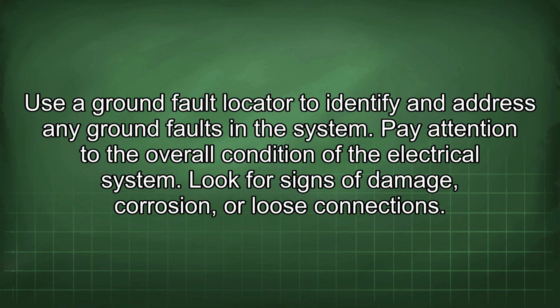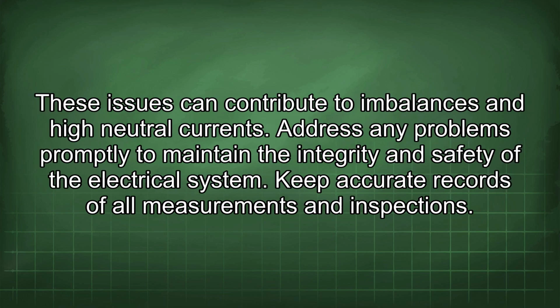Pay attention to the overall condition of the electrical system. Look for signs of damage, corrosion, or loose connections. These issues can contribute to imbalances and high neutral currents. Address any problems promptly to maintain the integrity and safety of the electrical system.